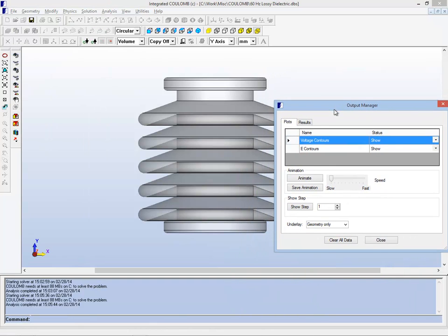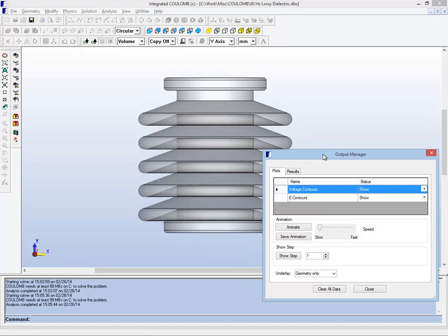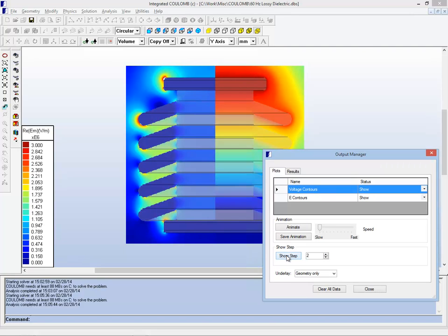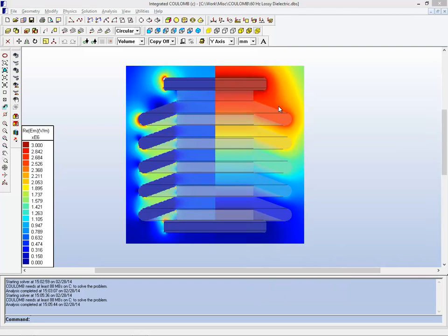Now we can look at the voltage and the field both for the initial problem, this is the plot we saw before, and for the much higher conductivity but still quite insulating situation we changed it to. What you see is that the shape of both the voltage and the electric field have changed quite a bit. Now the voltage divides almost evenly running down the middle. That is, the color is changing uniformly down the center.